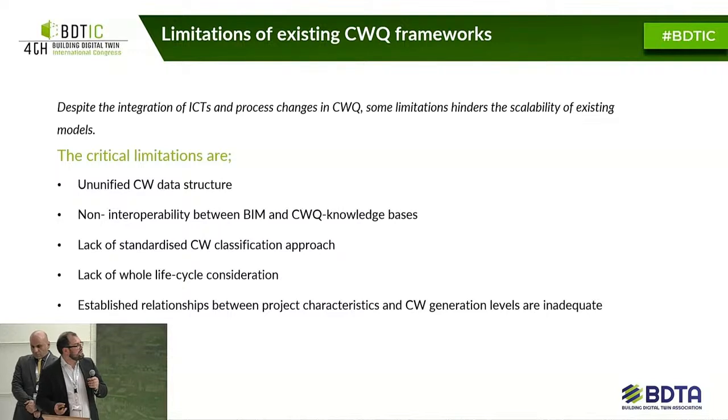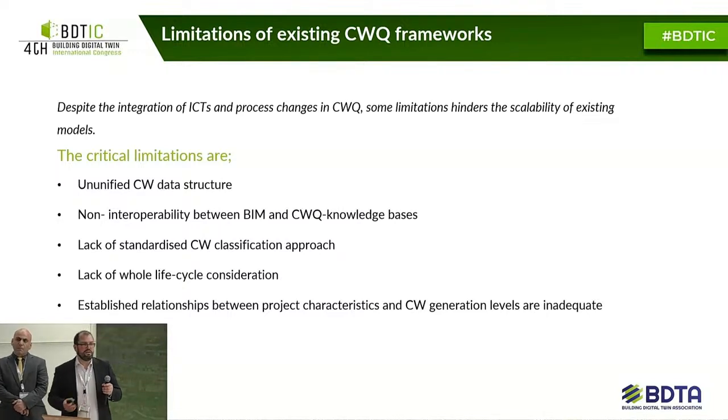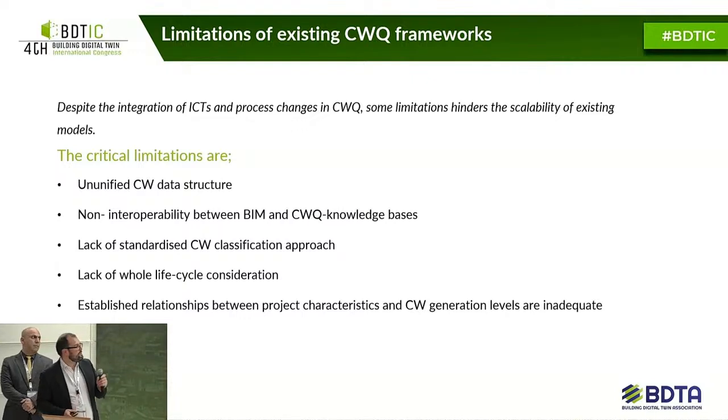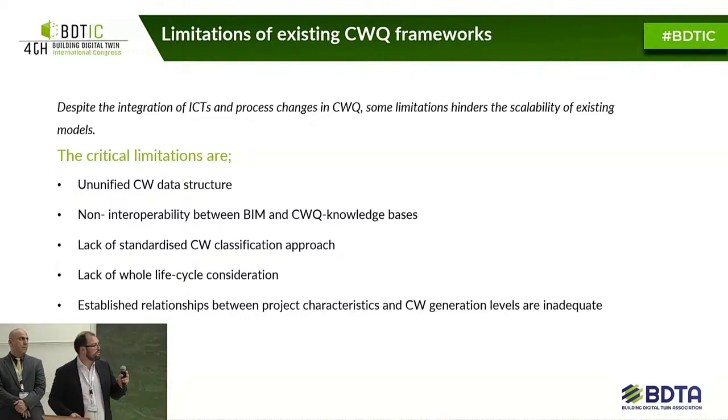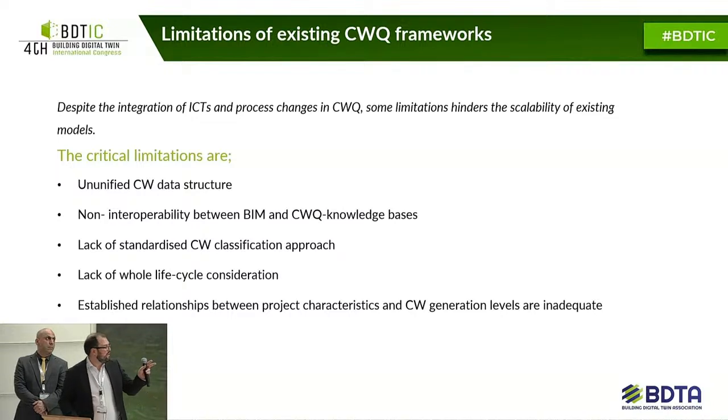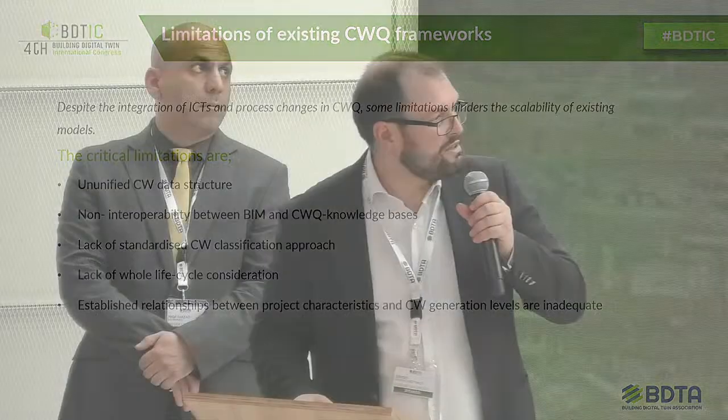There's a lack of a standardized construction waste classification approach in the world. You might be using the same materials, but it works better at cluster level, at local level. There's no real interoperability, or there are very few projects that have interoperability between BIM and construction waste management, quantification methods, and knowledge bases. And we lack a complete whole life cycle approach. And finally, establishing the relationship between the project characteristics and construction waste generation levels is inadequate, so the type of identification is kind of random or arbitrary.